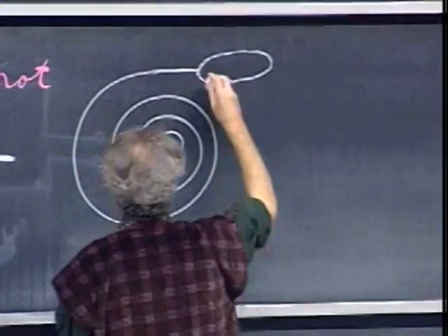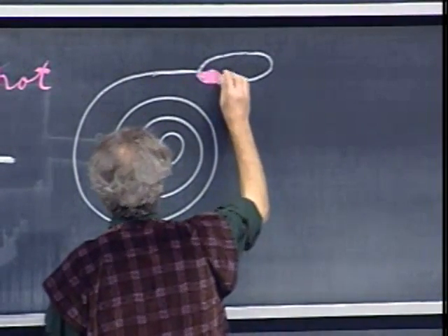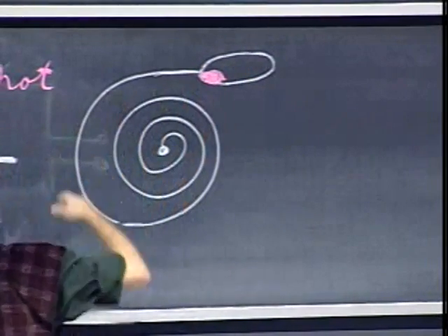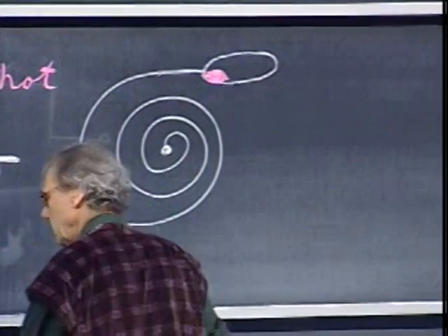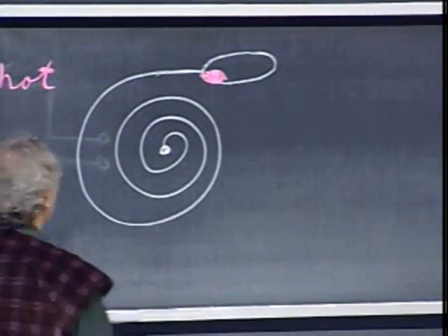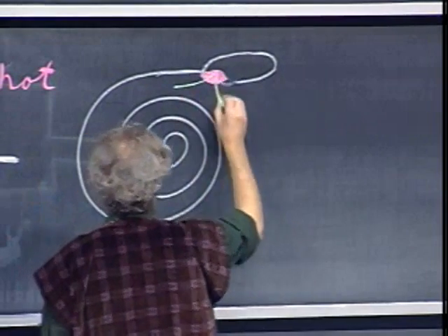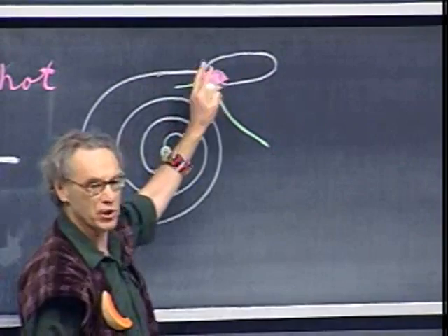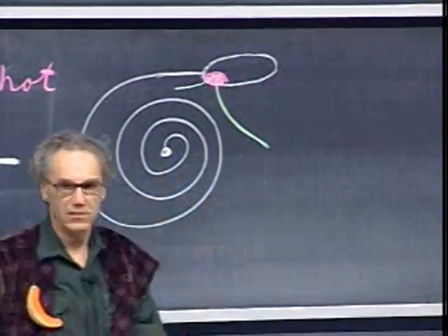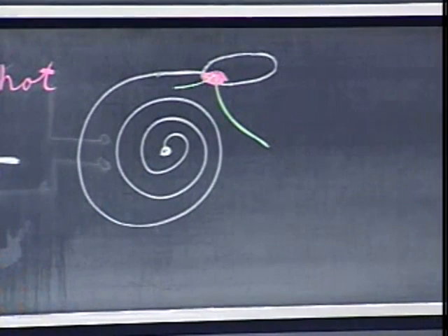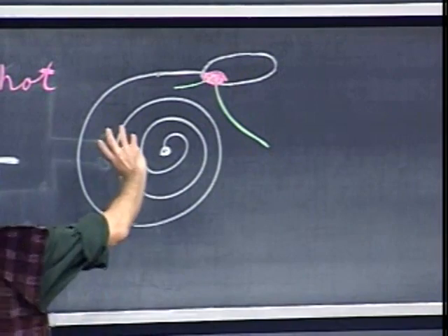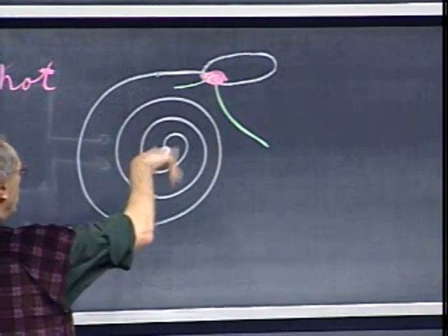And the mercury is here on this side, because notice the way I have tilted it a little. The mercury rolls to the left. And there are here 2 wires, electric wires, one here and one here, which go to the heating system. And so when the mercury is here, which has a good conductivity, the heater is on. Now the room gets warmer and warmer and warmer, and the bimetal will tighten up, will curl even more.